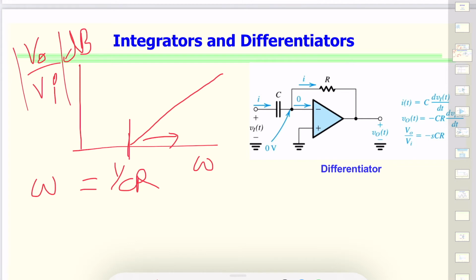So if you think about it, we should see that the nature of a differentiator circuit would cause it to be a noise magnifier, because a spike is introduced at the output every time there is a sharp change in the input voltage. That could be interference coming from somewhere, any signal picked up from adjacent signal sources.